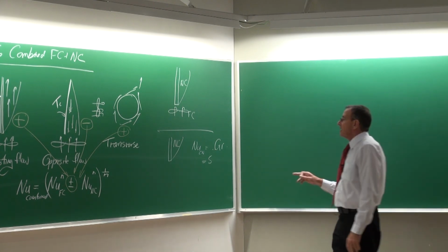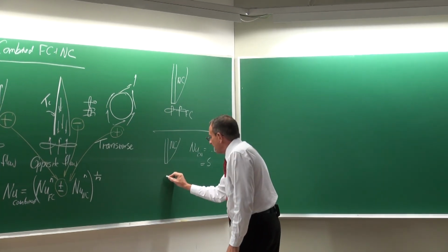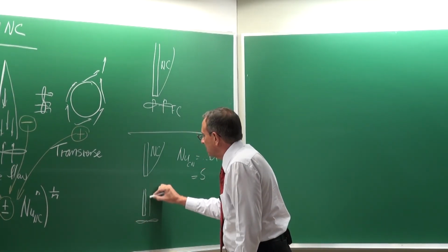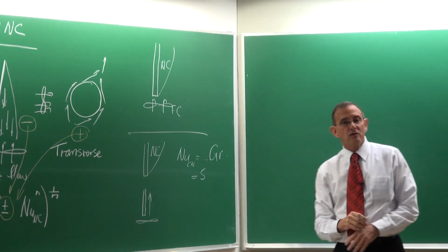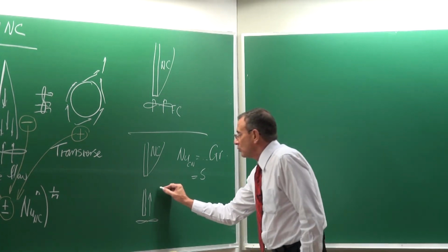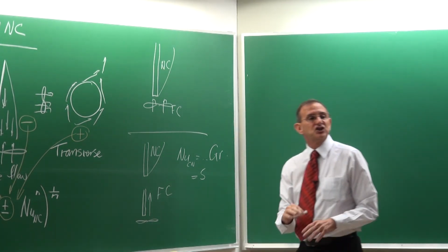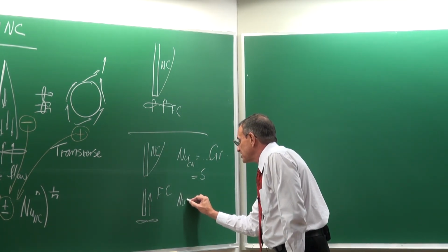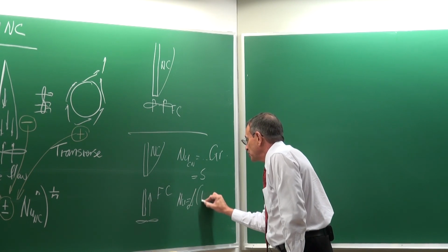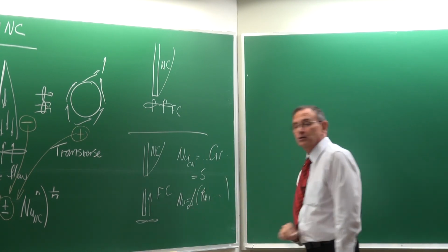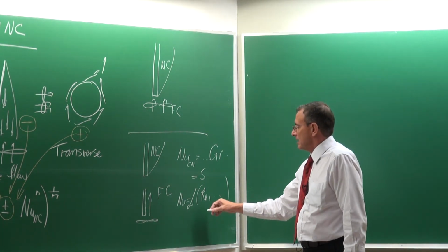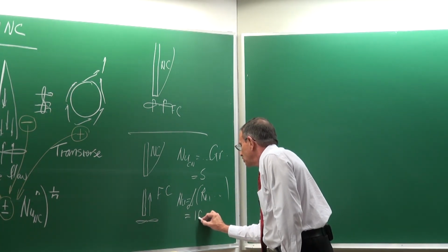And then you would ignore that part and you would say, well, this is a flat plate and I've got a fan and the flow is over the plate. So I would consider this as forced convection only. And I will go and calculate the Nusselt number. It will be a function of Reynolds number. You've done it already in chapter 5 or something like that. Now let's suppose this value is equal to 10.